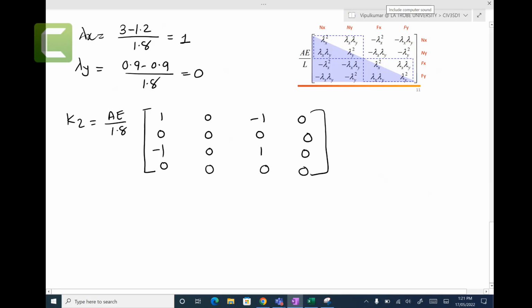Not by copying, but when you do the calculation, do the rechecking, okay? Check these rows and columns, because it's a symmetric matrix. Again, these 4 here should be the same here. These 4 here should be the same here. So you never get it wrong. You do a double, triple checkup. And then you give this one 1.8, so 1 divided by 1.8 gives you 0.56.